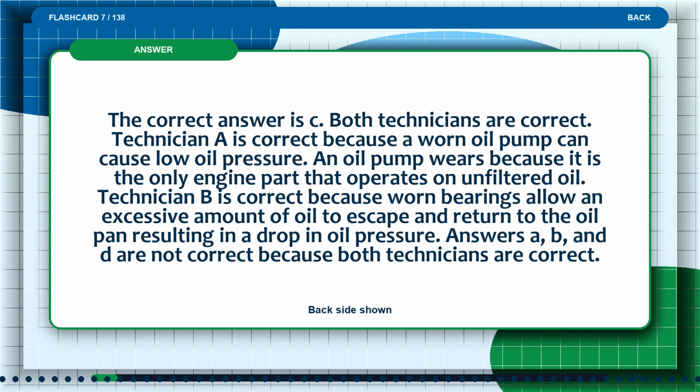The correct answer is C. Both technicians are correct. Technician A is correct because a worn oil pump can cause low oil pressure. An oil pump wears because it is the only engine part that operates on unfiltered oil.